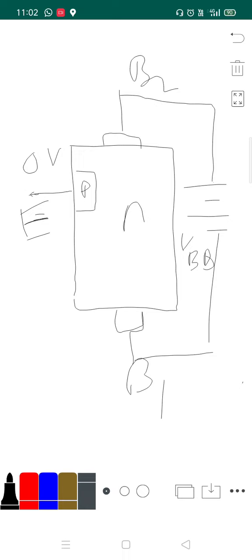As the emitter is open, at 0 potential, the PN junction is in reverse bias. A small leakage current flows from B2 to the emitter due to minority carriers. In this reverse biased configuration, the width of the depletion layer will be increased.